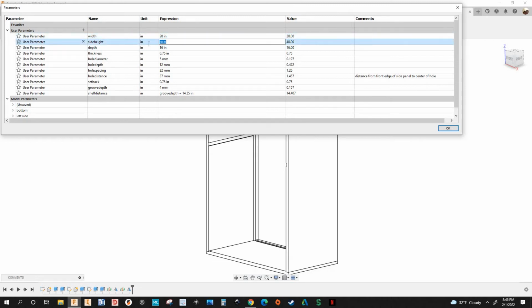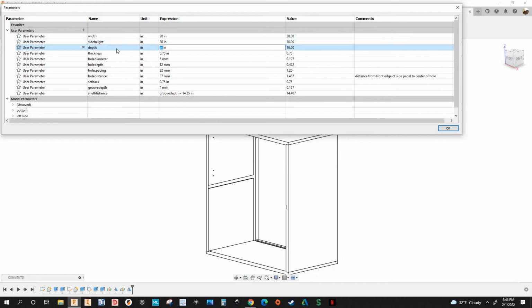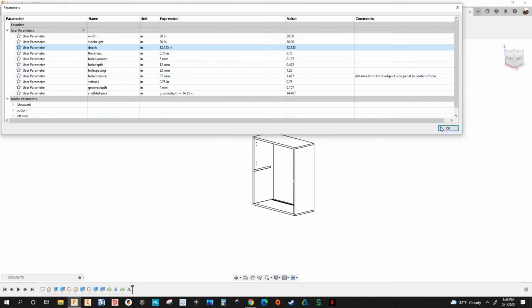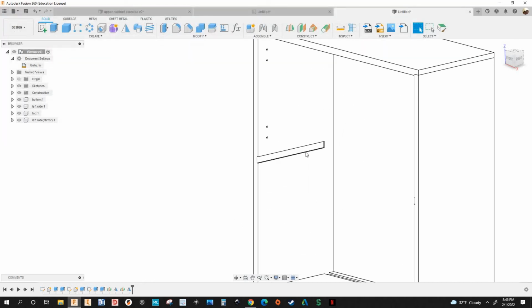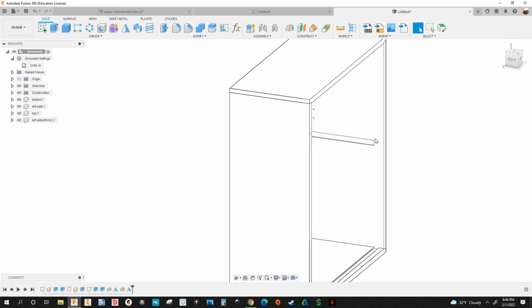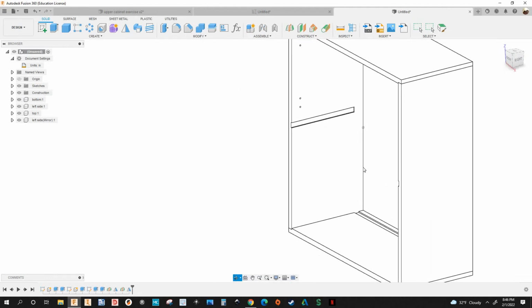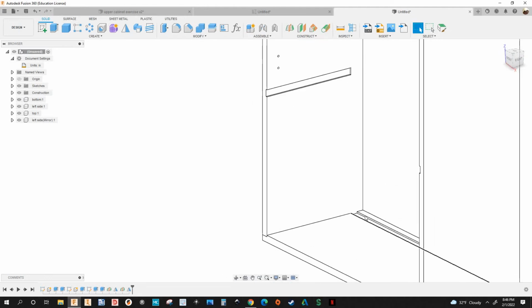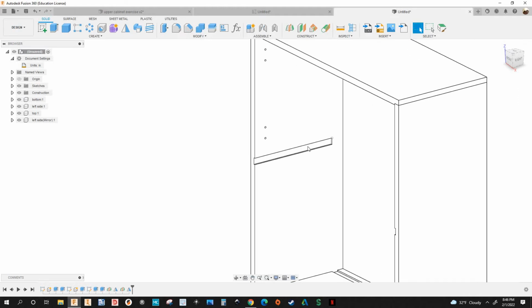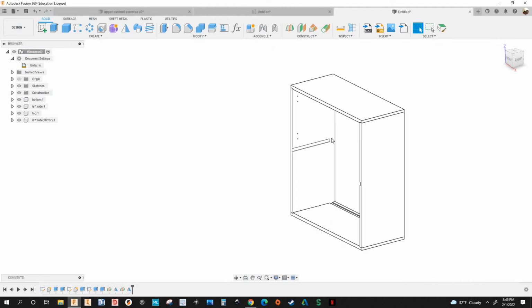and the side height to 30 inches and the depth back to 12 and 8, 12.125. Hit enter. Okay, we see what happened here. See that? That's fine because remember the back panel is gonna go right there. It's gonna go up. Okay, so it's gonna intersect with this groove right here for the fixed shelf.